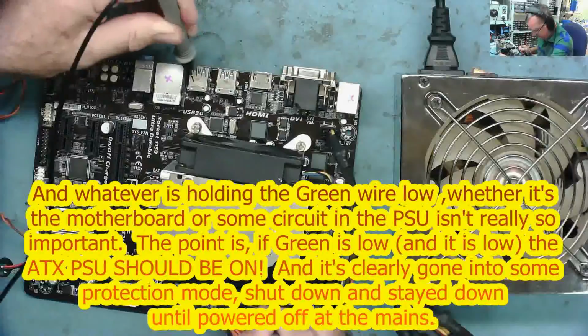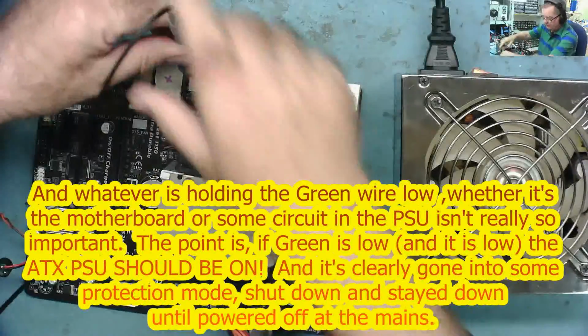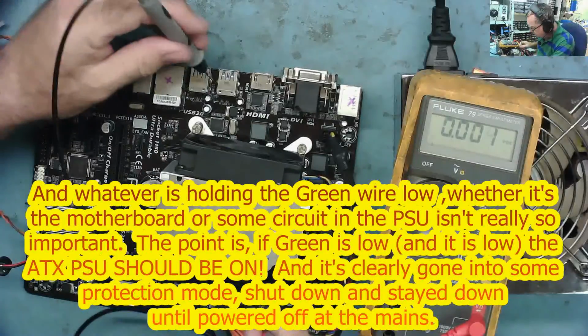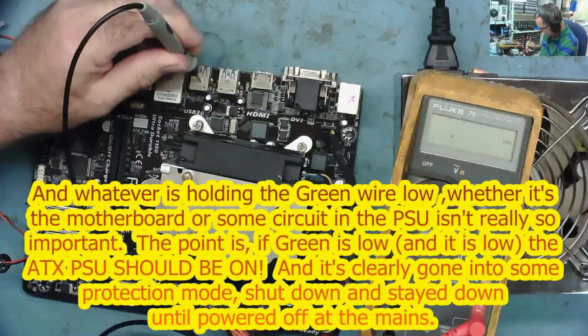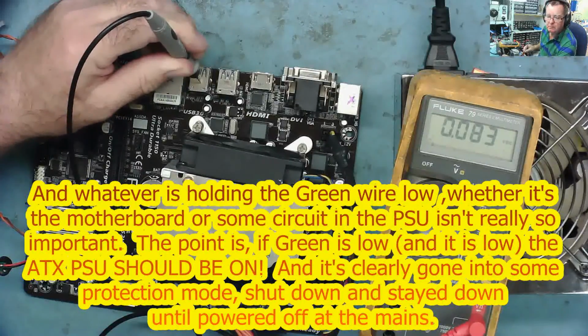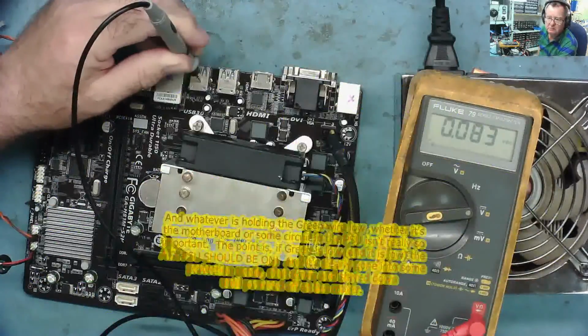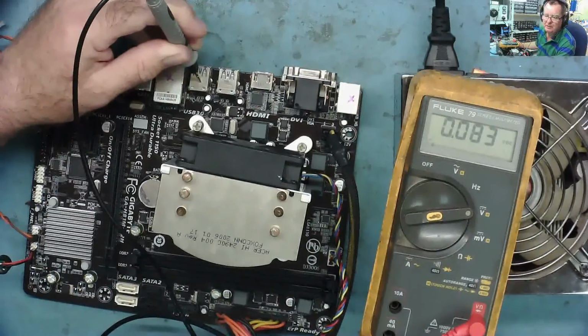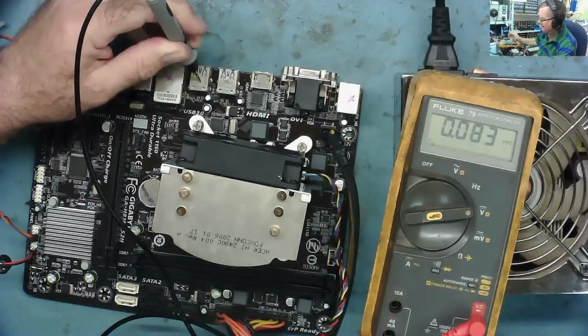The 5 volt standby is there. Sorry, I've got the meter where you can't see it. The 5 volt standby is there, but this is now low. Something's holding that low, so that means the power supply should be on and it's off. That's why it doesn't make sense.